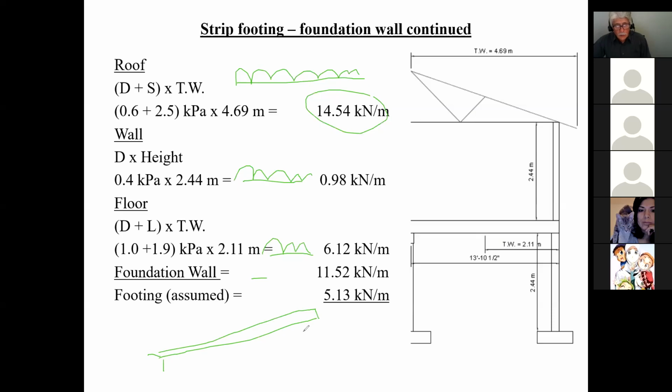All along the strip footing here, I have a distributed load acting along that footing, and that's of course going to be the last amount here of 38.29 kilonewtons per meter. That's how I calculate the load on my footing. Last year when we were doing strip footing, I said the strip footing has a live load of 1.5 kilonewtons per meter, and now you can actually calculate that.